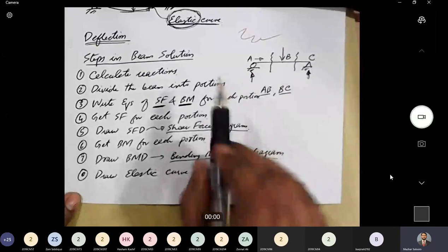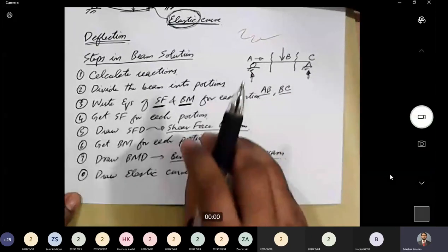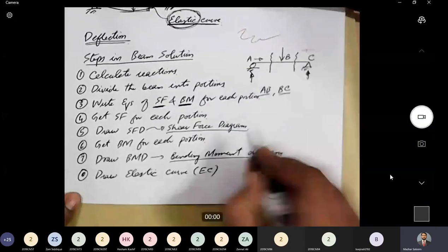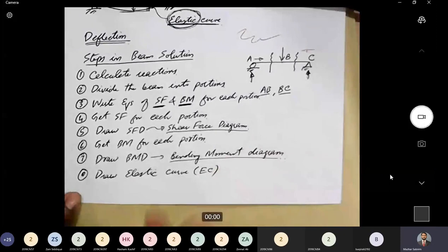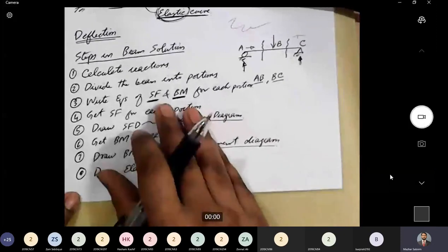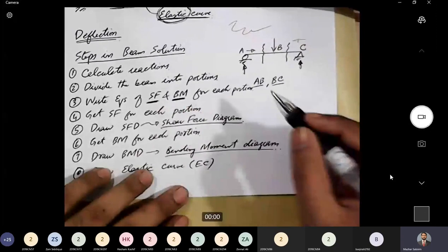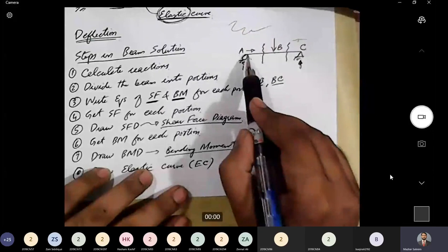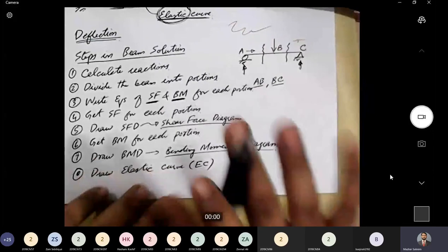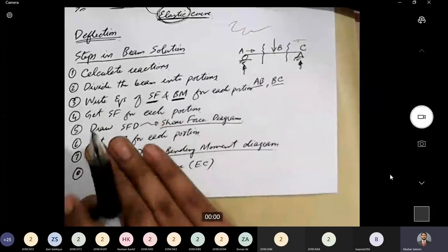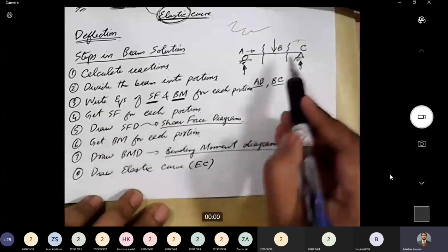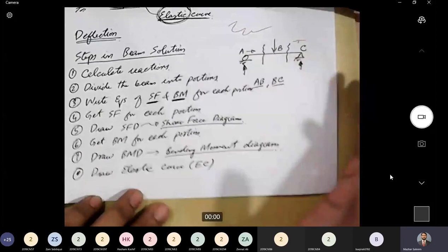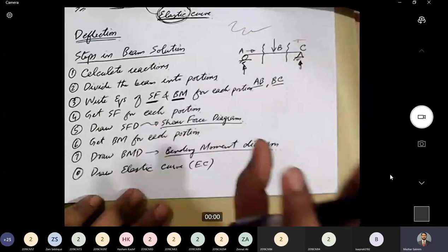Although it is possible to write down the equation of shear force and bending moment from both left side and from right side, as a beginner, we will be fixing one direction. We will always be writing down the shear force diagram and bending moment diagram equations from the left side. At some later stages, when we get a good hang of all these things, we will solve some problems from the other side of the beam as well, because in some cases it is convenient to approach the problem from the other side. We will discuss that at a later stage, not right now.